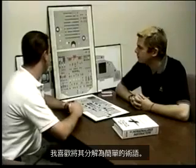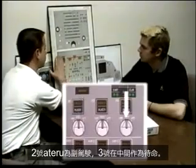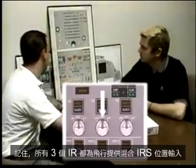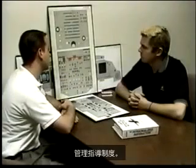Panel. I like to break this down into simple terms, and the way I remember it is IR number 1 is for the captain, IR number 2 for the first officer, and 3 is in the middle as a standby. Remembering that all 3 IRs provide a mixed IRS position input to the flight management guidance system.